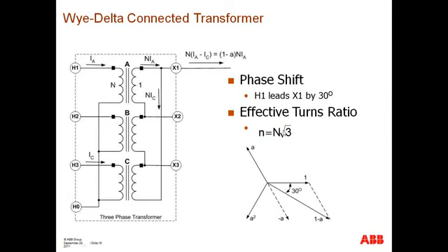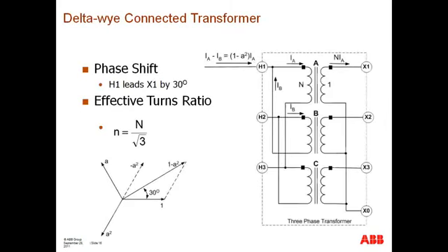And then the delta connection is utilized on the generator side of the equation, so that, again, we provide that isolation between the zero sequence networks in such a way that if a phase-to-ground fault occurs within the generation station, the transmission network does not become a source. And this is a decision that's made because, as we've discussed on other webinars in this series, most of the faults are actually phase-to-ground faults.